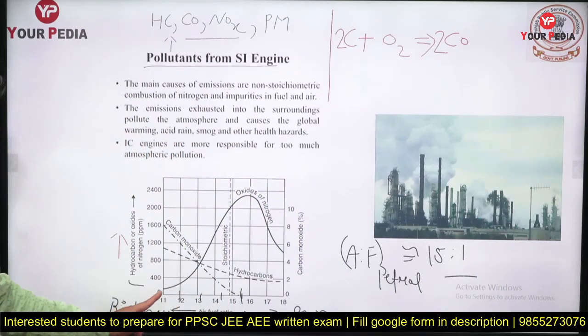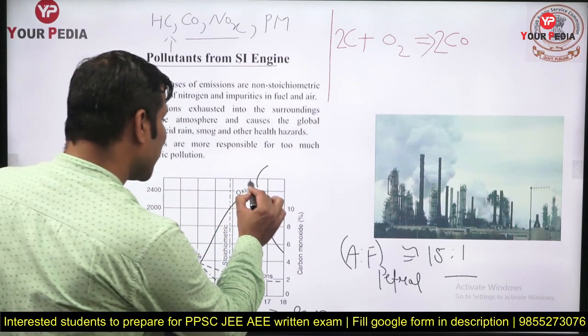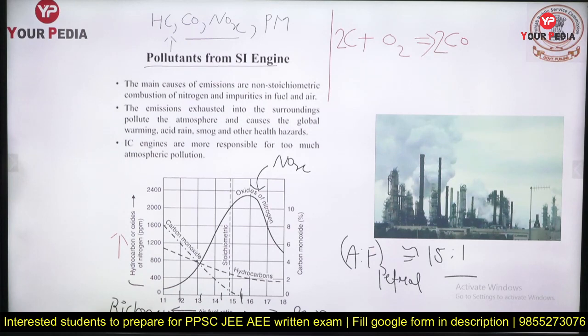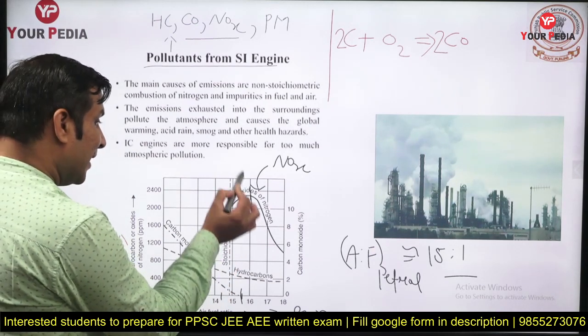One more thing guys, you need to understand here is the NOx emission, the nitrogen oxide emission, oxides of nitrogen, which are known as NOx. They will have the maximum value. NOx emission will be maximum with a slightly lean mixture guys.